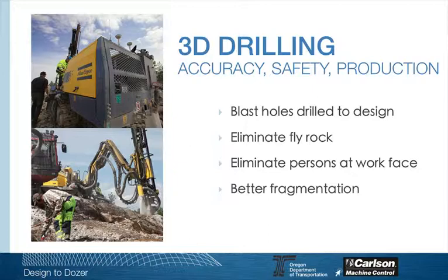If you blast inappropriately or not according to design, which can occur by inaccurate drilling or blast hole angles that are not exactly parallel, you affect the entire downstream process. The rocks are too big, the material's too big, it has to be broken up. You stress the wheel loaders or track loaders and trucks that move this material away. So these are some of the desired benefits, and 3D machine control can enhance all of these.